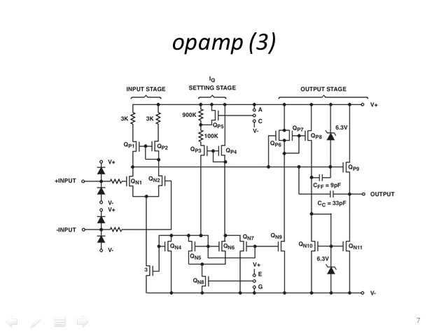Our output stage does both amplification and then provides output currents such that the system can source and drive larger loads. You'll also notice that there are capacitance networks to set the stability, these Miller capacitive compensation networks to improve stability of the operational amplifier.